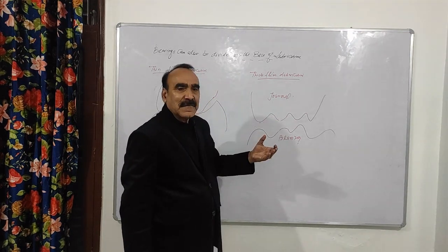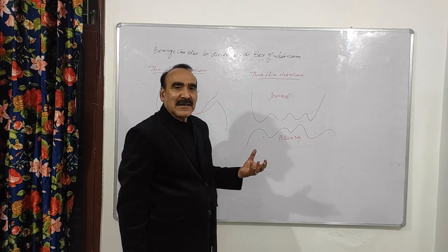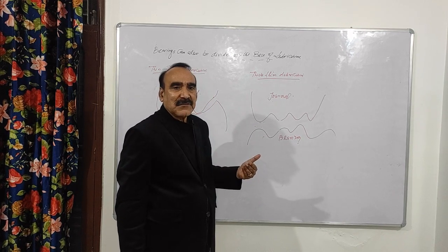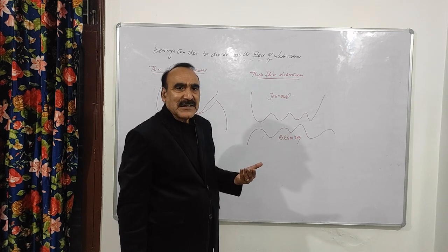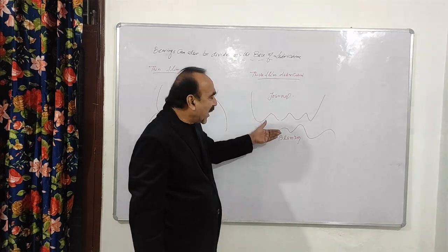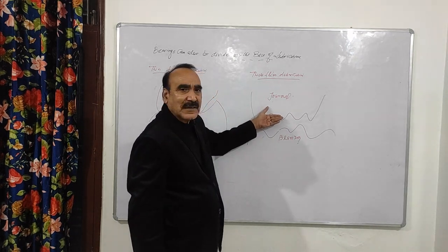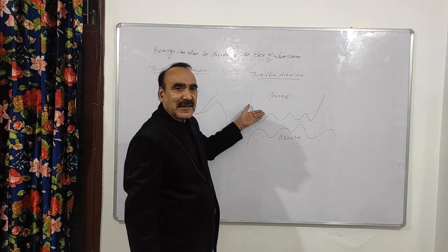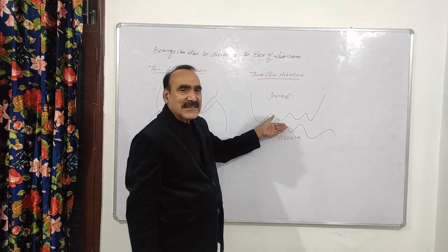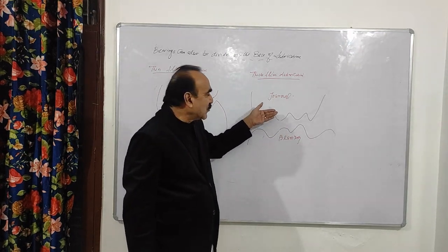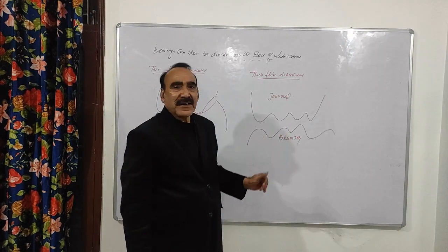What it means is that we have increased the pressure, we have created the pressure here. So with the pressure, that pressure will help to lift the base of the journal bearing, or that has taken the load of the journal and that has made it separated from the bearing surface.